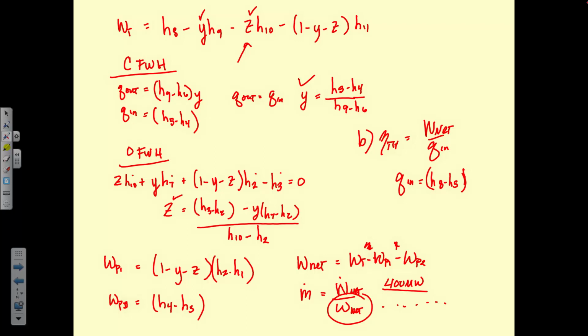How do I find another equation? It may come in the terms of doing an energy balance on a heat exchanger or a feed water heater or a mixing chamber, or looking at your throttling device again. You just have to see what you have and what other pieces of the puzzle you haven't analyzed yet. So anytime there's a heat exchanger or a mixing chamber or anything else where multiple fluids are coming together, maybe the turbine, then you can do another energy balance or a mass balance or sometimes both to figure out what pieces you don't know.